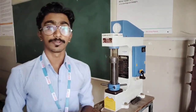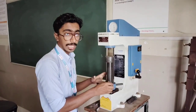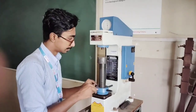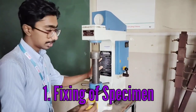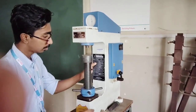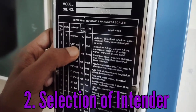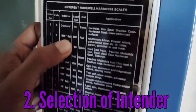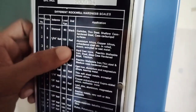First we will rotate this anvil towards the upper side, and then according to the table, as I am using aluminium, I will select an indenter of 1/16 inch and apply a load of 100 and see the red dial.